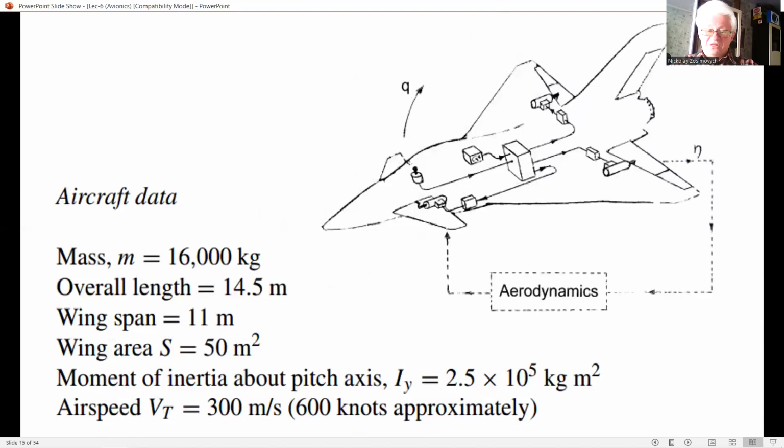It is thus necessary to attenuate the FCS loop gain at the structural mode frequencies to avoid driving the surfaces at this frequency and exciting the flexible mode. This slide illustrates the frequency response of a typical notch filter, so called because the gain versus frequency graph has a notch shape.